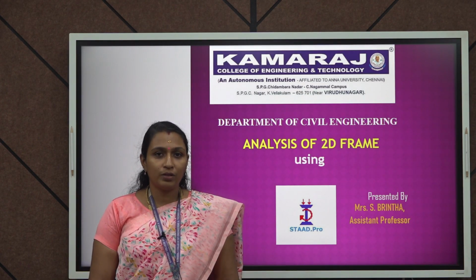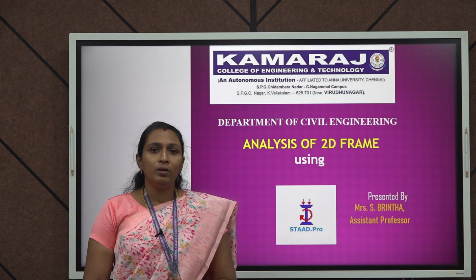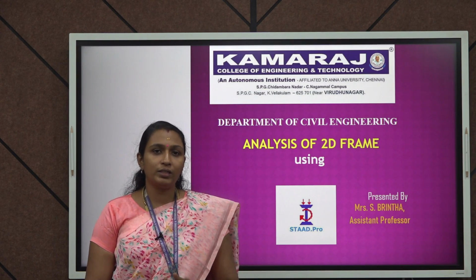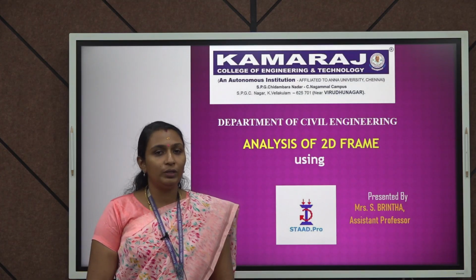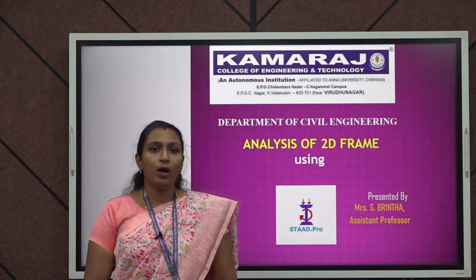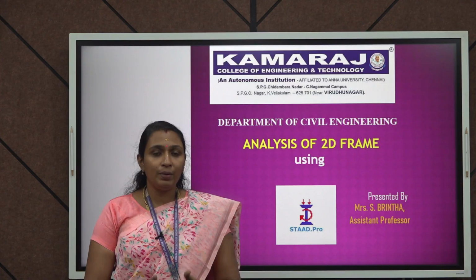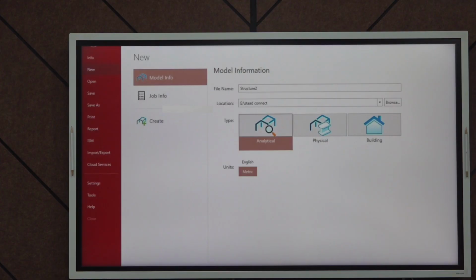There are two types of frames, rigid as well as braced frame. We know everywhere we shall see the general frames which are constructed as rigid. There are some structures which are constructed with braces. The purpose of adding braces is to avoid the collapse. Adding braces to columns is to avoid buckling of columns as well as indefinite or immediate collapses, or to avoid unexpected collapses. We now open the model.